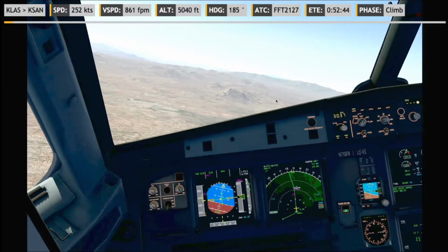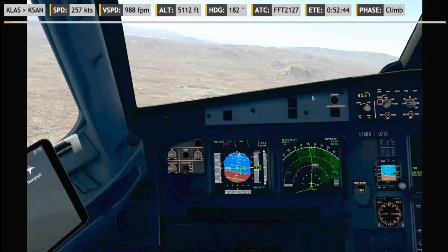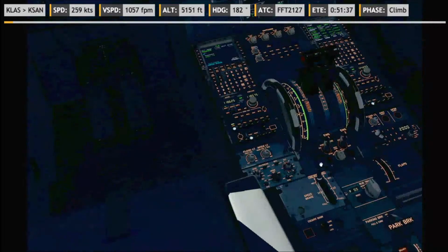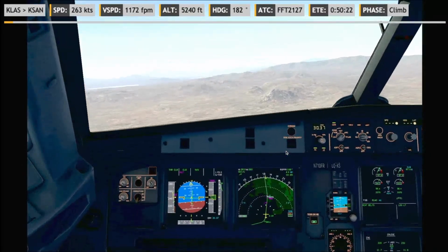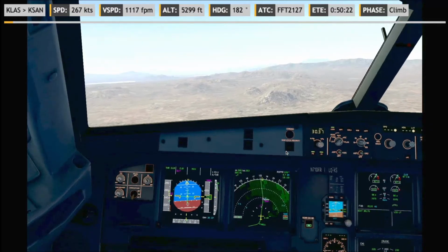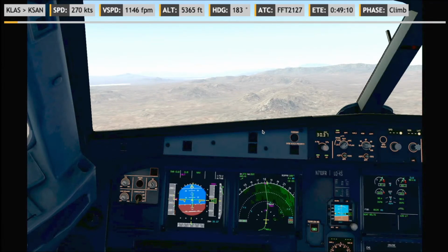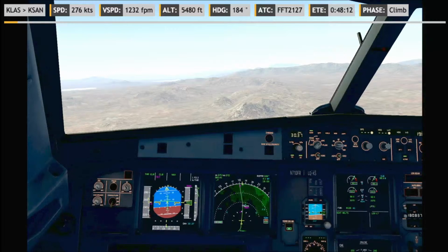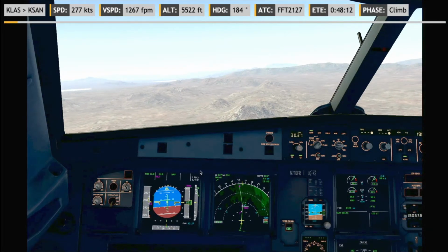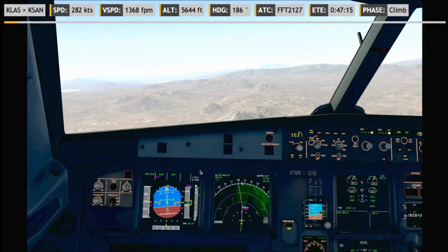Alright, after takeoff: lights, speed brake, initial items checked, and we'll do our checklist soon. Right, climb restricted up to 7,000 initially via the SID. It's indicated here. I have it on my chart as well. At Roper we want to be between 4,800 and 7,000 feet.